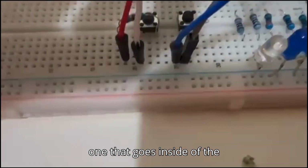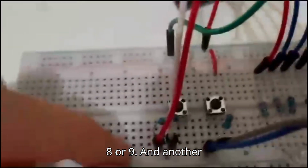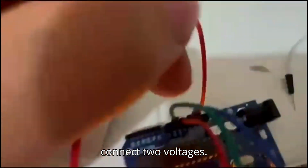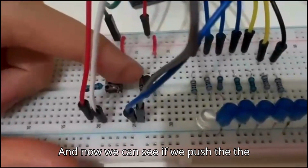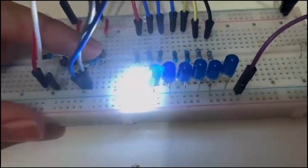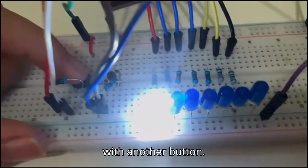This one that goes inside of the button, we connect to pin 8 or 9, and another one that goes outside of the button, we connect to voltage. And now we can see if we push the increase button it goes up by 1, and we can decrease with the other button.